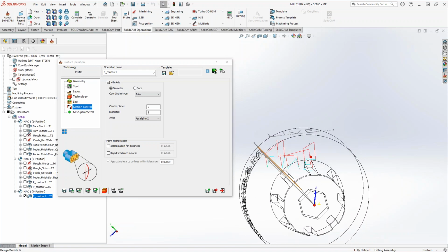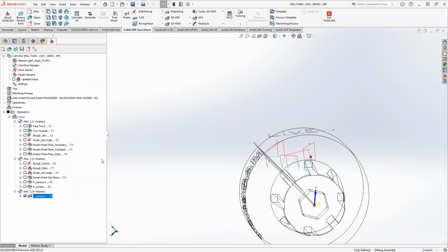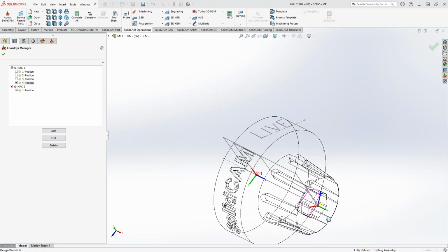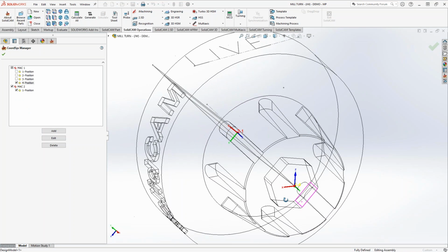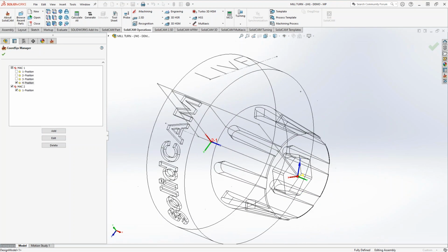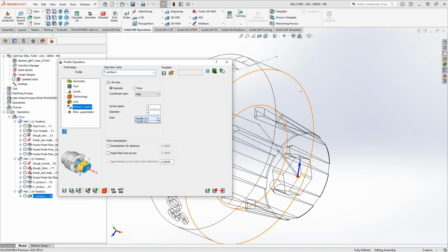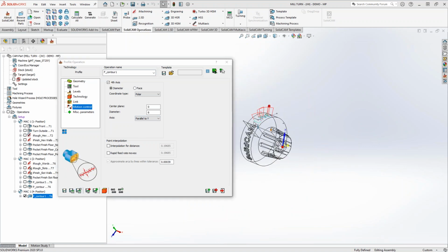wrap geometry, but in the wrong direction. Let me just double check which direction the x-axis is in Mach 1 position 4. And there it is. So it's incorrect, because I just assumed that it was the x-axis. In this case, it should have been the y-axis. So apparently when I made this, I wasn't following my own rule of thumb. But let's go back in there and just make the correction. Just go y. And there it is.